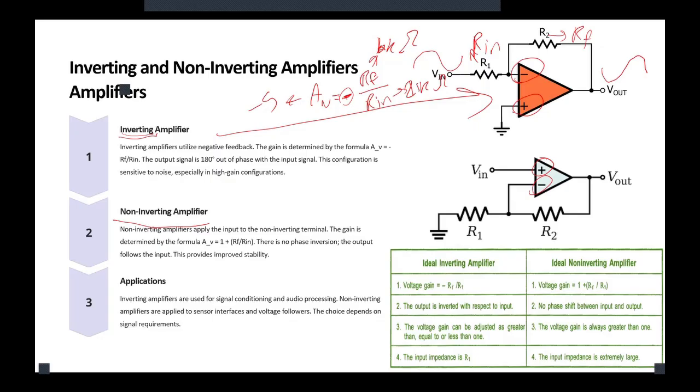Because we want negative feedback so we can control and make sure of the stability of our circuit. There are going to be resistors to do that. Now, the inverting pin is also grounded using another resistor.